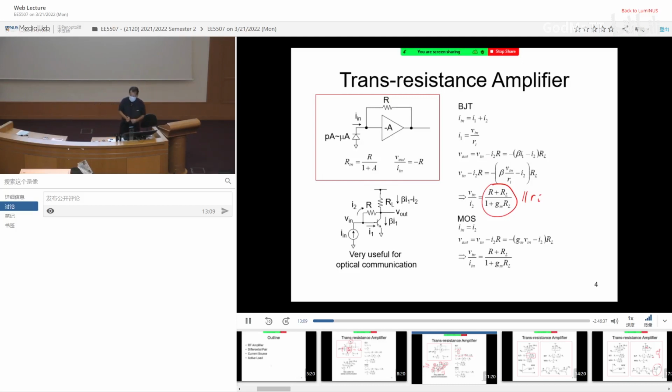Now MOSFET is simpler. If you try to replace this guy with MOSFET, you don't even care about I1, because I1 is not there. All you need is simply I2. So In becomes I2. You go through the same thing: your Vout can be obtained first looking at Vin, and then going through the I2R drop.